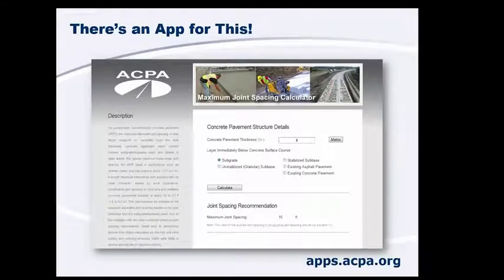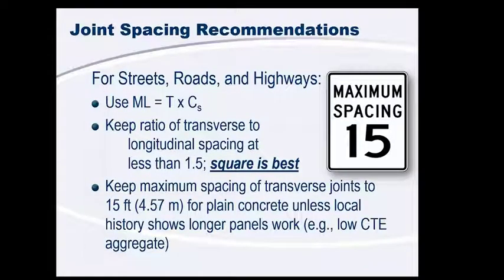If you don't really want to remember those support constants, there's an app for that. If you go to apps.acpa.org, you can find the maximum joint spacing calculator. It's a free app. It's really easy to use. You basically just put in your thickness and define your layer immediately below the surface, and it'll spit out your maximum joint spacing. So a few other recommendations for our maximum joint spacing.